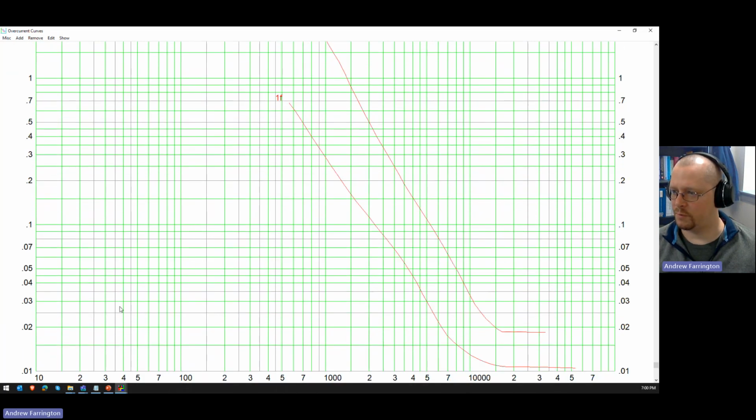And this is why, because of this graph plot. You can see that the more current you get, the relay operate time goes down. So at 3,000 amps you get an operate time of 0.07 seconds, but at 1,000 amps you get an operate time of 0.28 seconds.